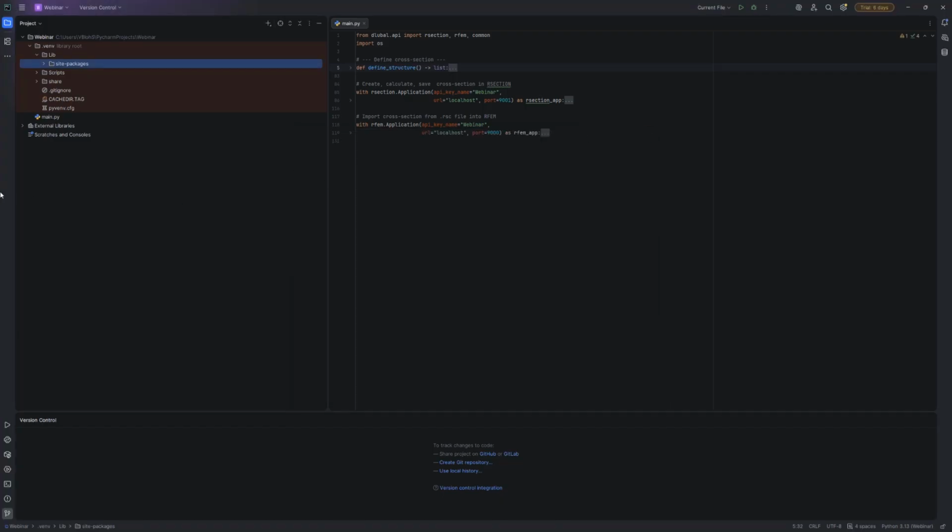Furthermore, the Dlubal API package must be installed. Make sure that the Dlubal API version matches your installed program version to ensure compatibility. For example, Rsection version 1.13.0005 requires Dlubal API version 2.13.5. The crucial point is that the last 2 digits, this means 13 and 5, of the version numbers match.